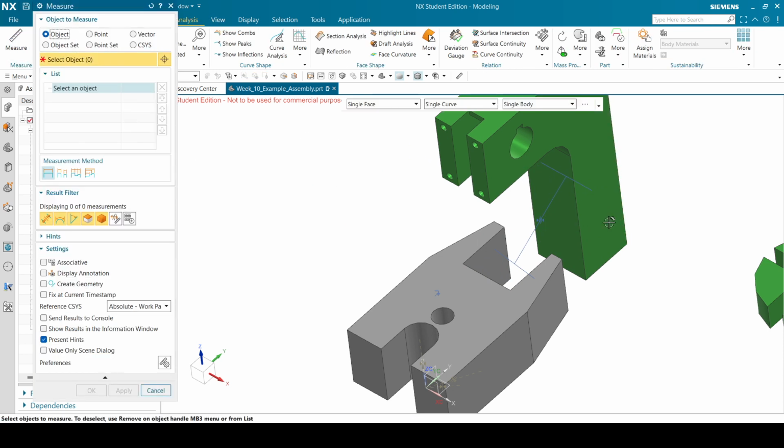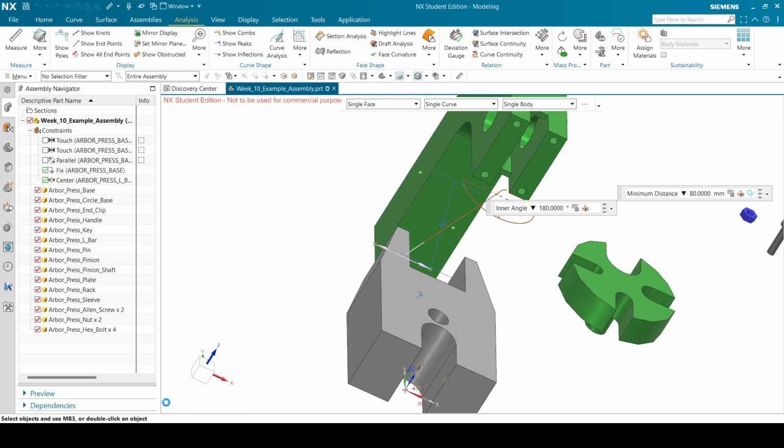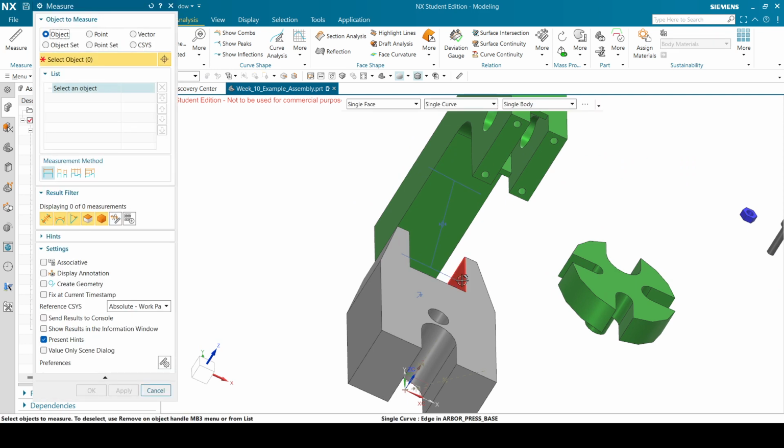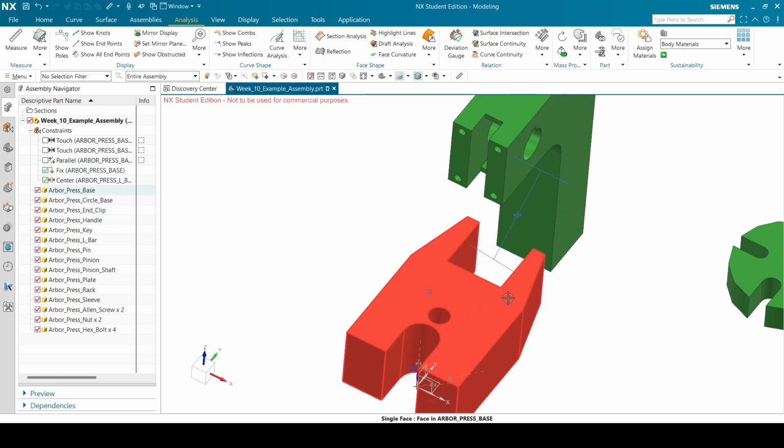For this part, let's quickly check. This distance, which is 80 millimeters, should be the same as this distance. Yes, but in the real world, you have tolerances. So this one will be a bit larger than this one. If you create an assembly that has parts which have tolerances, then you use center to make it a bit more neat and make it line up theoretically perfectly. So you don't already misalign it when you have the option of doing it correctly.